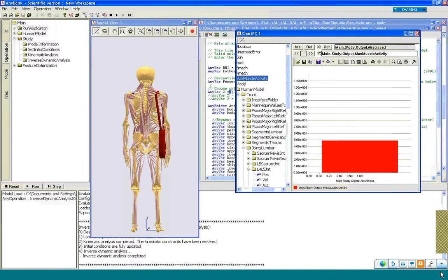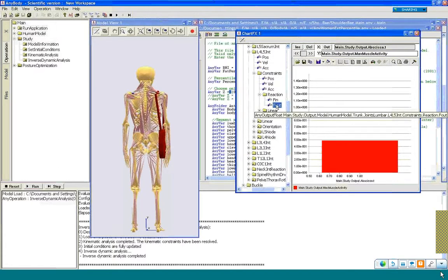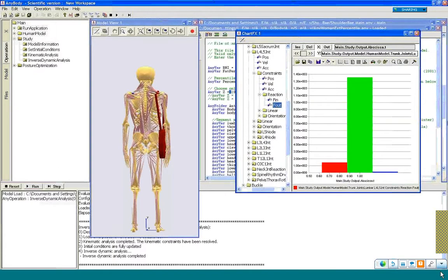Are we expecting that they should be smaller or larger for the small female? Well, if we go down and plot the number, we can get something like this. And you can see here that the value is now about 1,350. So the compression in the small female spine is actually about 50 Newton higher than it was in the large female spine. So it does look like, because of the smaller moment arms of the spinal muscles, it's probably that which is playing a role here.